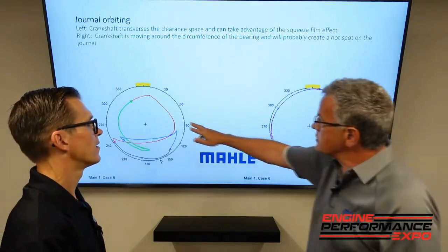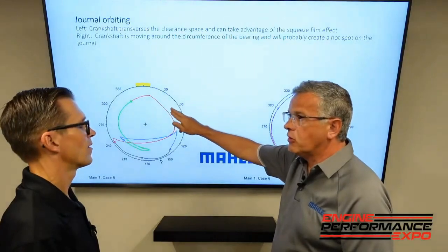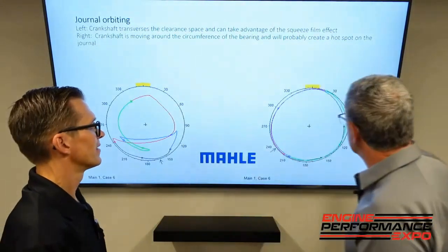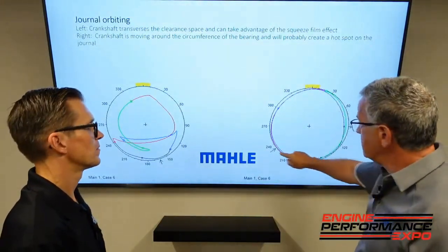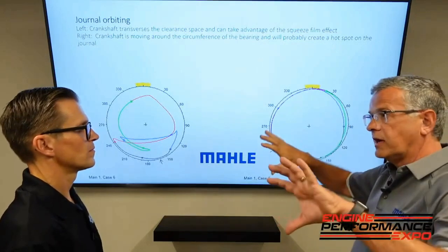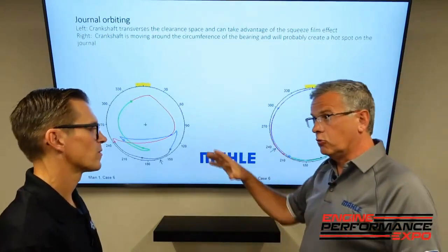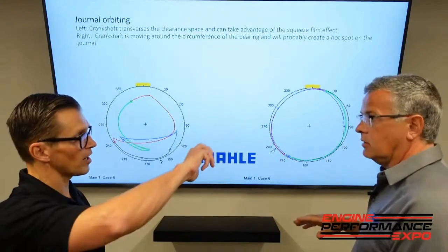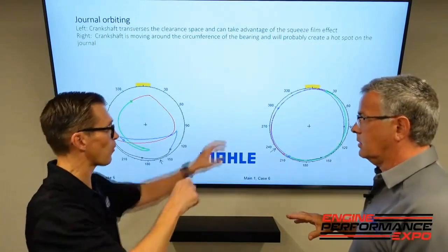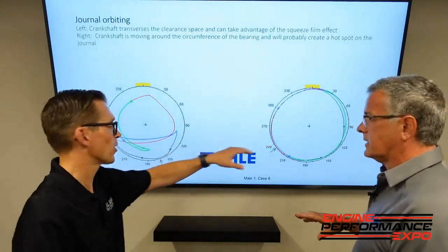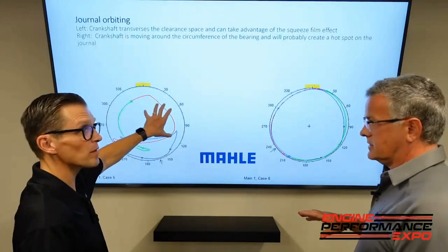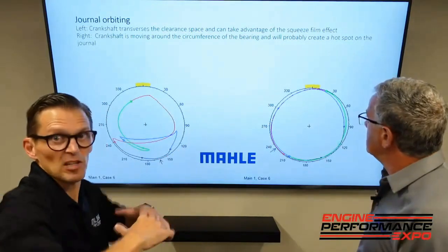Okay, so you notice there's no places for it to fill oil into the wedge, because they're all void because of how close it's running, because the crank now all of a sudden in simulation grew. Essentially, yeah. It's like turning off the valve. You're not letting enough oil flow across the face of the bearing anymore, because there's not enough running clearance anymore. Exactly. Because the flexing is taking up the clearance.